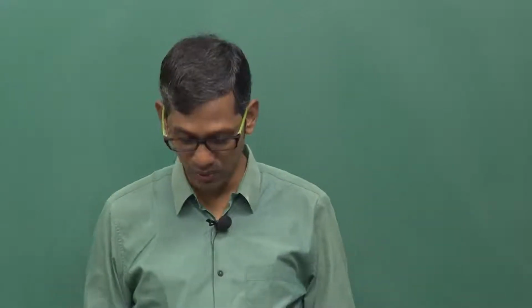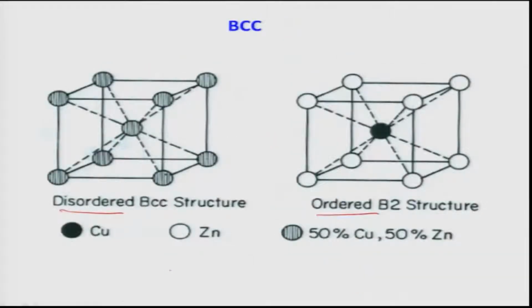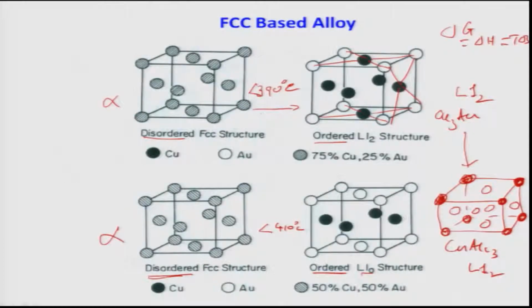Which are the 110 planes here? Let us go back to the crystal structure. You see, this is one of the 110 planes. So if I draw a body center, which is along 111 directions, the body diagonal basically, then half 111 displacement means one atom going from here to the central atom, on this half 110 plane here.